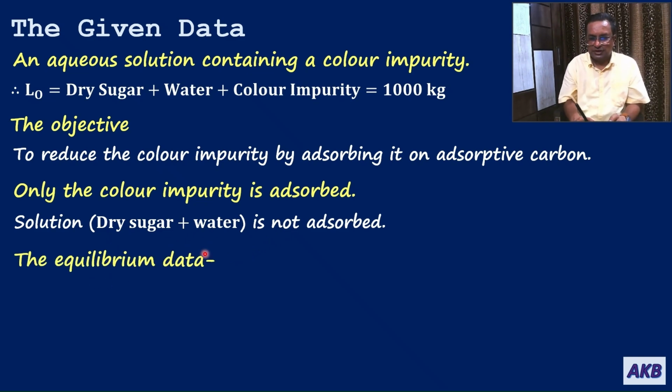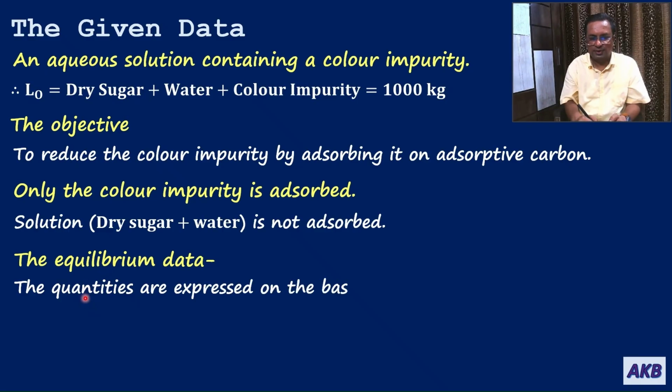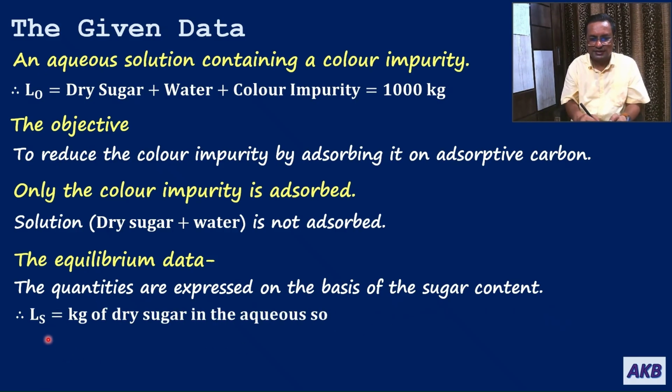In the equilibrium data that is given to us, the quantities are expressed on the basis of sugar content, kg carbon per kg dry sugar. So therefore, in this case, LS is not kg of solution. LS is the kg of dry sugar that is present in the aqueous solution. That is what you have to remember, since the equilibrium data is given in that form.